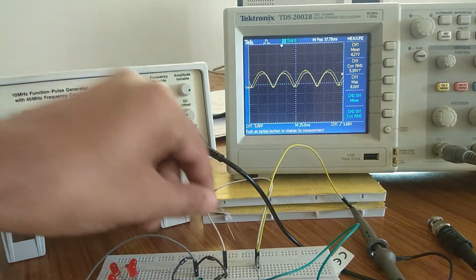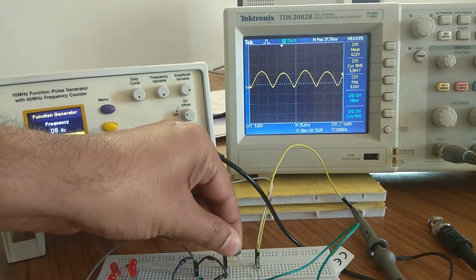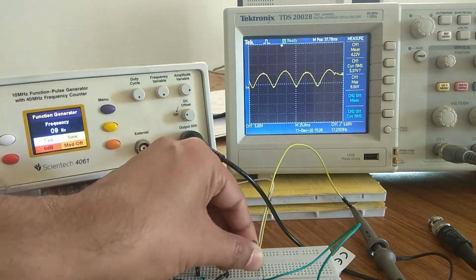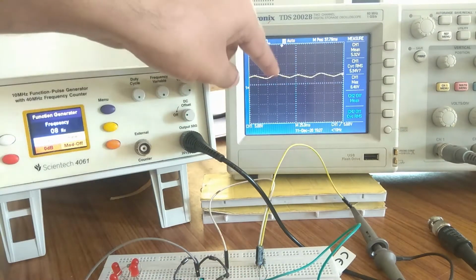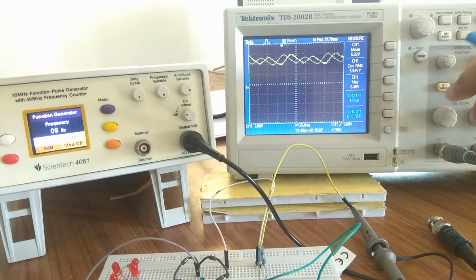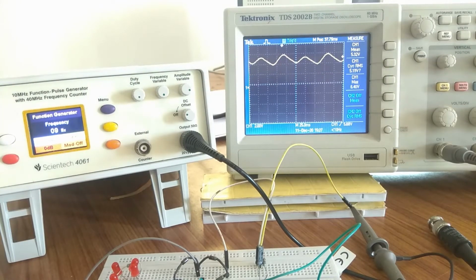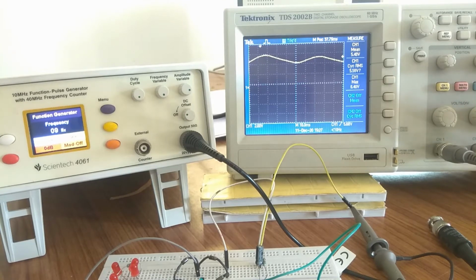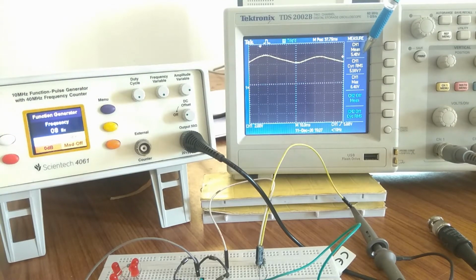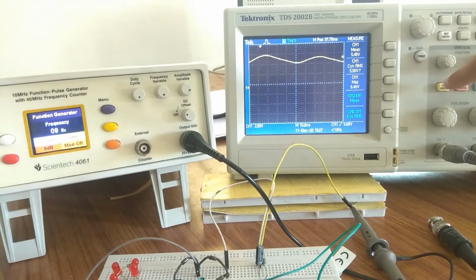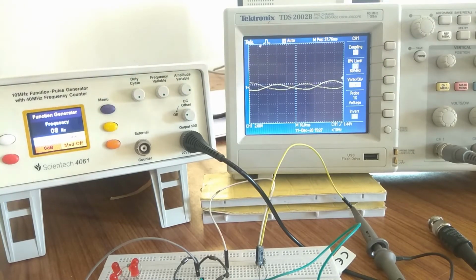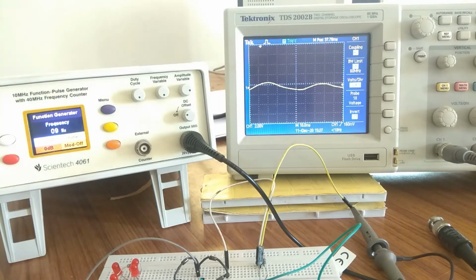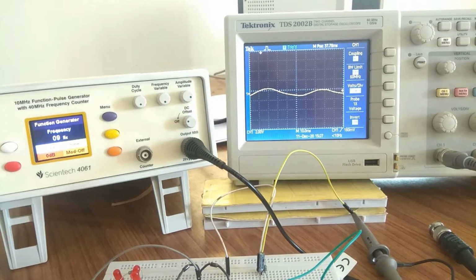Now whenever I insert this capacitor, if you see, your output is going to change. This is the output that we were getting. If you want to enlarge that output, this is how we enlarge. For exact calculation, we make it so that it is around 5.48 and 5.56. And for the measurement of the AC component, press channel 1, go to AC coupling, and this will give you the AC coupling. Now we are going to see the result and see the changes in the ripple factor and the efficiency.